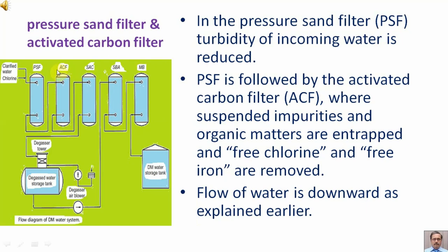In the pressure sand filter PSF, turbidity of incoming water is reduced. PSF is followed by the activated carbon filter ACF, where suspended impurities and organic matters are entrapped and free chlorine and free iron are removed. Flow of water is downward as explained earlier.